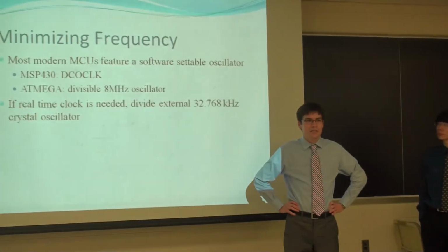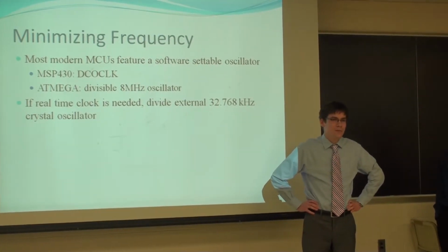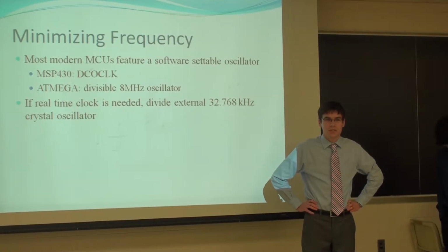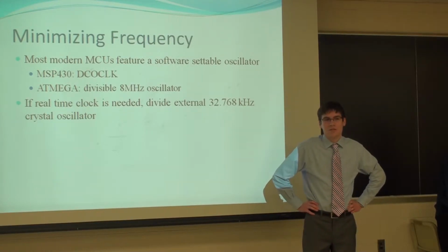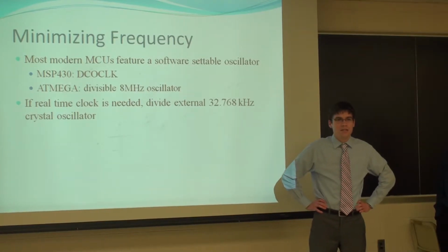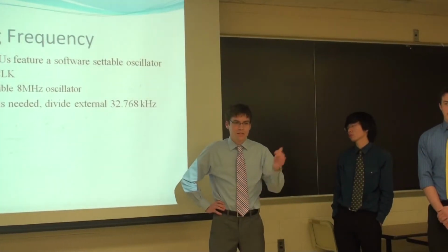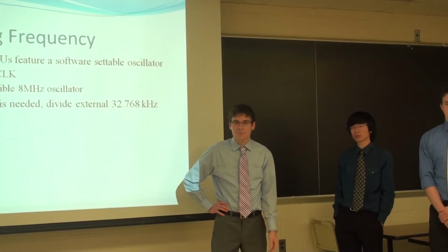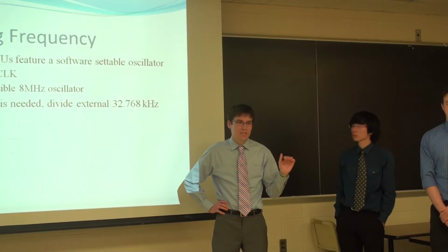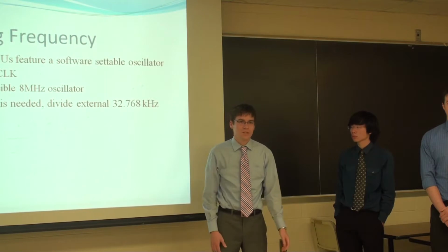Corey began to introduce the fact that a lot of the current that's consumed in a CMOS device is consumed during switching, and so the idea of reducing frequency to minimize power is that by executing fewer instructions per second, you're having fewer switching operations, and since voltage is held constant and power is a multiple of voltage and current, you're reducing your power.